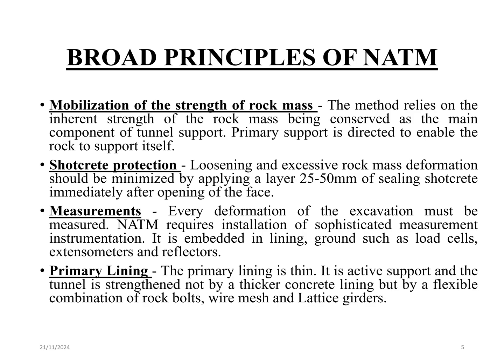Let's discuss some important principles of NATM. The first principle is mobilization of rock mass strength. This method relies on the inherent strength of the rock mass being conserved as the main component of the tunnel support. The second principle is shotcrete protection. Applying a layer of 25 to 50 mm of sealing shotcrete immediately after opening the face to minimize loosening and excessive rock mass deformation. The third principle is measurement.